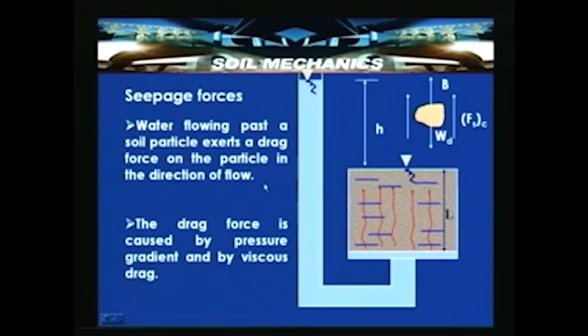of flow. So, it depends, for example, if it is happening in the downward direction, then there will be an increase in the packing of these particles because they are tucked into closer positions. So, there will be an increase in the effective stress. In the case of upward flow, the particles will be disturbed, and in a way there will be a reduction in the effective stress.